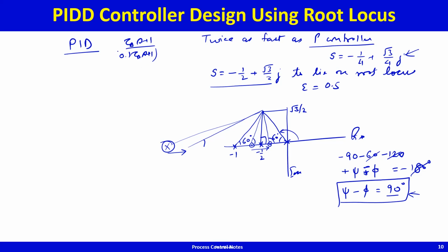Electrical circuits that implement this kind of a lead lag are typically standard, and they'll have numerator time constant as tau d and the denominator time constant as 0.1 tau d, not 0.05 or 0.01 tau d. Therefore, using a single derivative lead lag, it is very difficult to satisfy the angle condition.